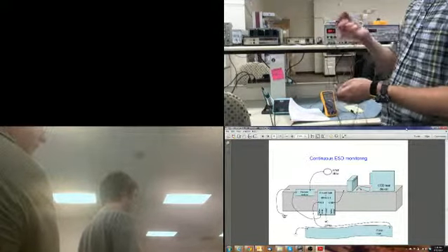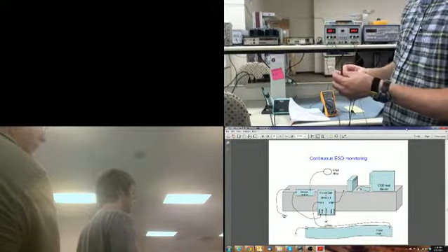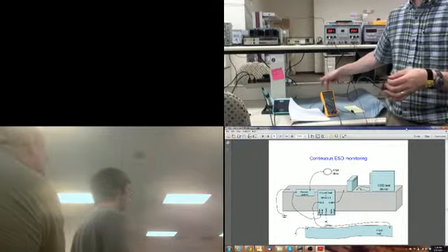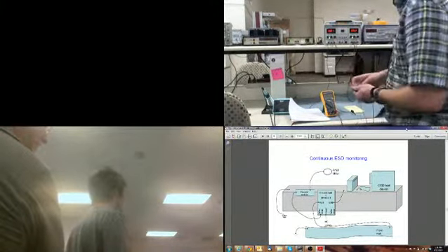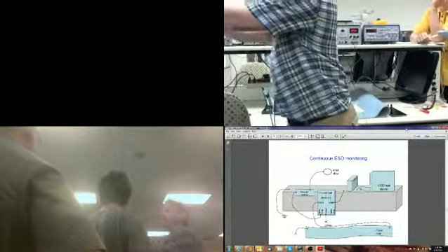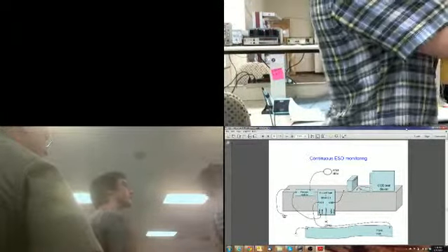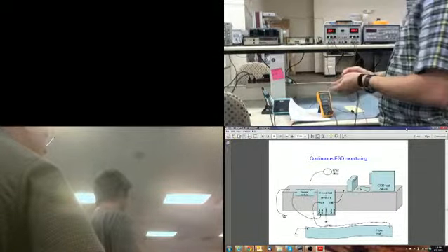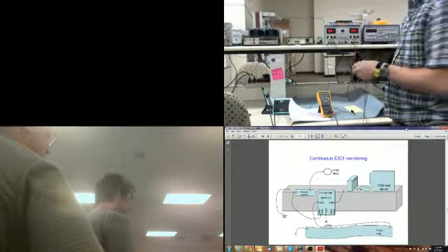Sometimes these things may be bad, so if you're troubleshooting, sometimes you need to measure. When you measure these, make sure it's not electrified. If it's electrified, it's going to screw up the reading. It's not going to give you a correct reading. Same with resistance. If you go to measure on this meter the ohm symbol, the Greek omega character, everyone knows that's the ohm symbol. If you put it on ohms, it's going to measure resistance. The higher the number, the better the insulator.